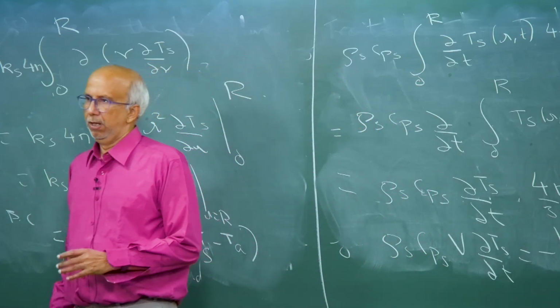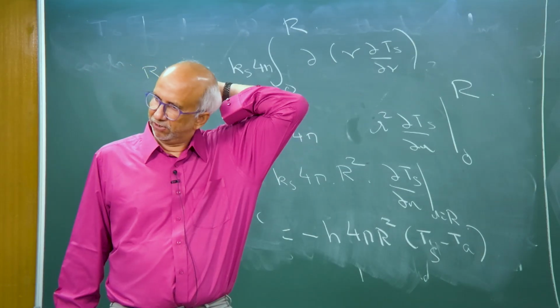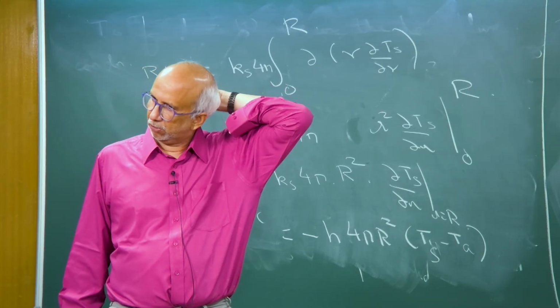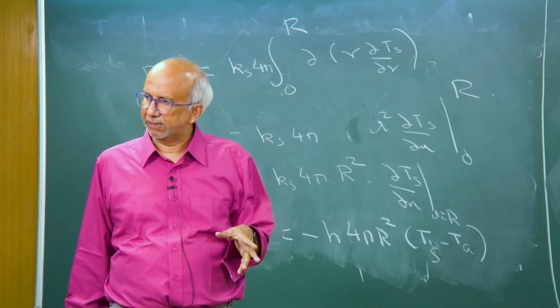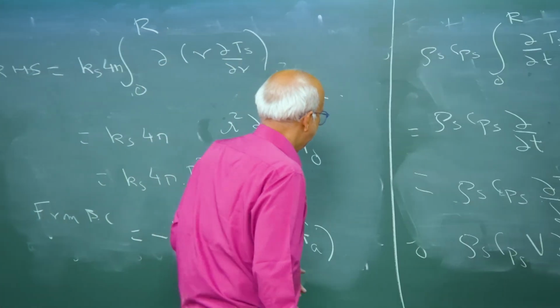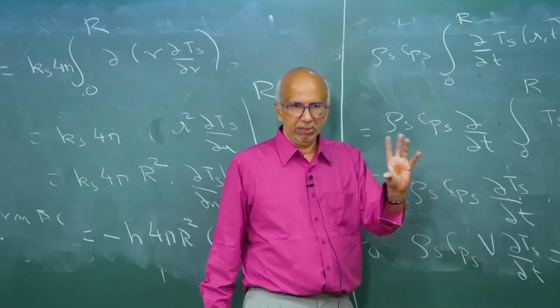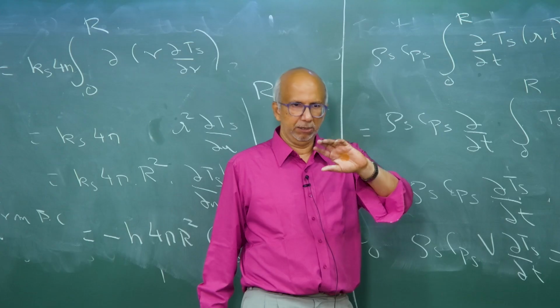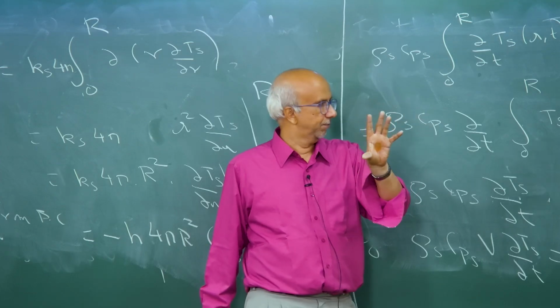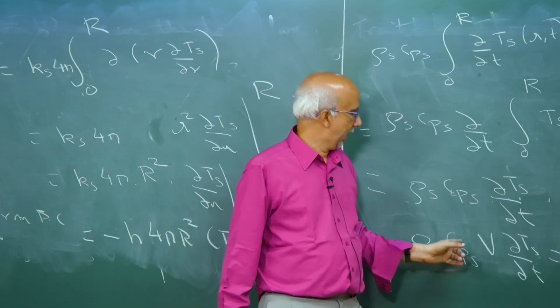Okay. So, this is possibly something which again you are comfortable with, familiar with in the context of transient heat conduction, you must have done in your BTech, okay, in your undergrad. So, what you got is called the lumped heat transfer equation, lumped because all the spatial variations are now neglected, or so from partial differential equation I have got an ODE now, okay, and I can use this.